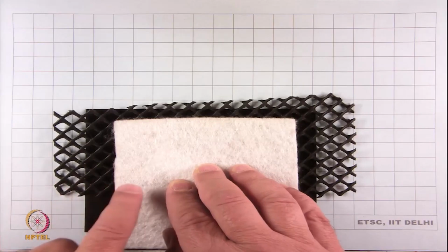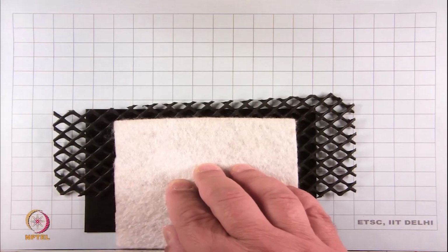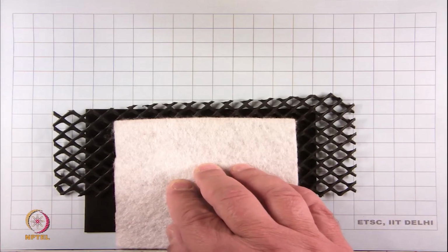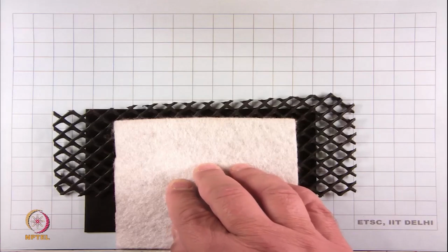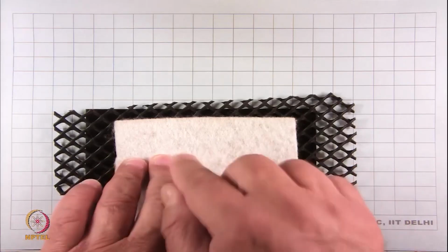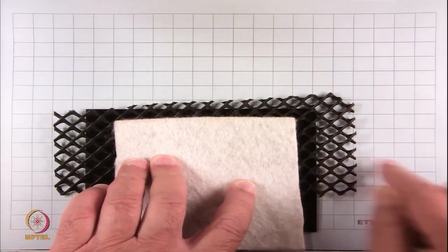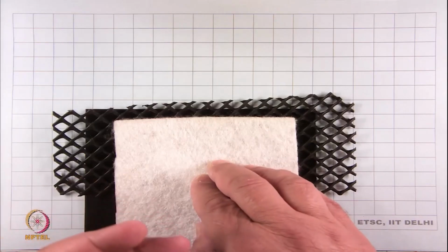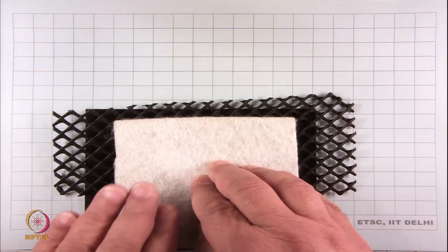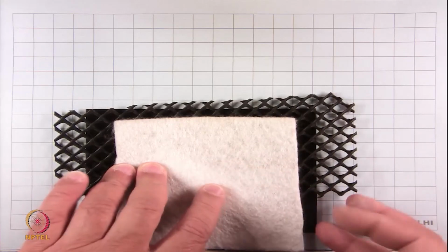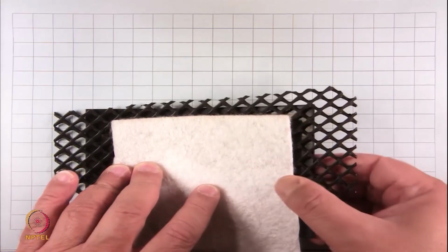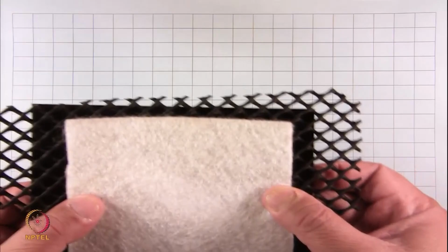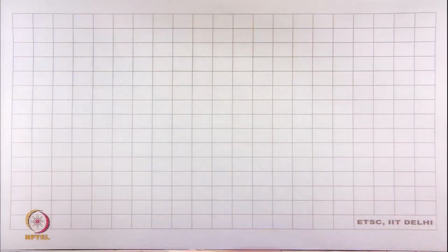But if this can replace the sand, something which is 5 to 10 millimeter thick replacing the sand, provided it has the capacity to carry the same amount of water as the sand that we had, right? So we will be dealing with issues of permittivity and transmissivity in this material, but this is one set of options. Now, so that it should not be difficult to install it in the field, we have something called a geocomposite.